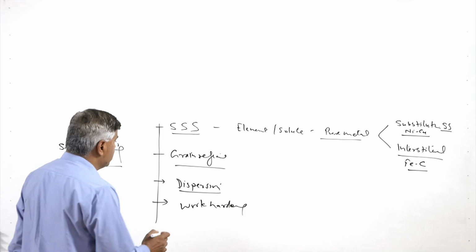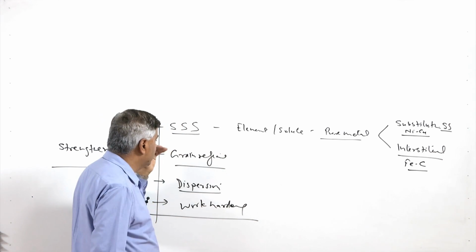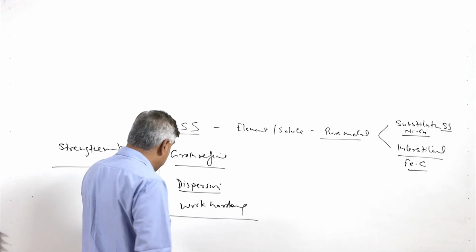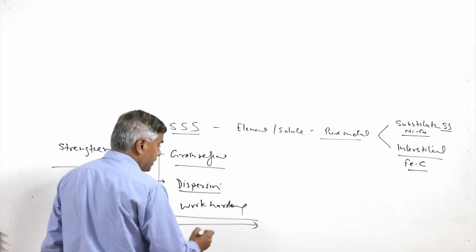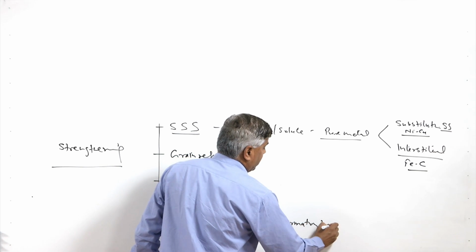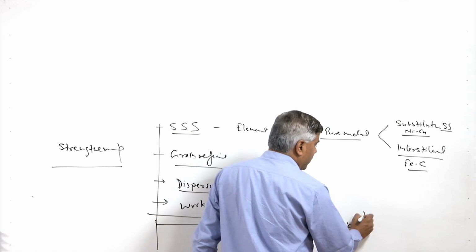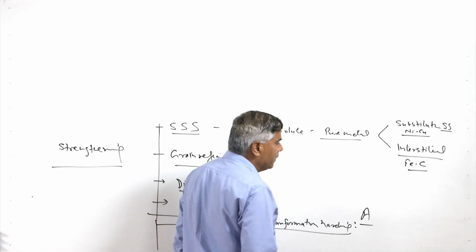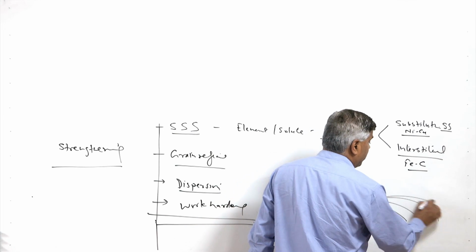So, these are the mechanisms which use different approaches like alloying, refinement, reinforcing with hard particles, or plastic deformation. Now, the two approaches about which we will be talking are related with heat treatment. The first is transformation hardening. This is typically used for the heat treatment of steels, where one phase like austenite, which is stable at high temperature, is unstable at room temperature conditions. So, using different cooling rates, efforts are made to have different kinds of phases, so we get different properties.